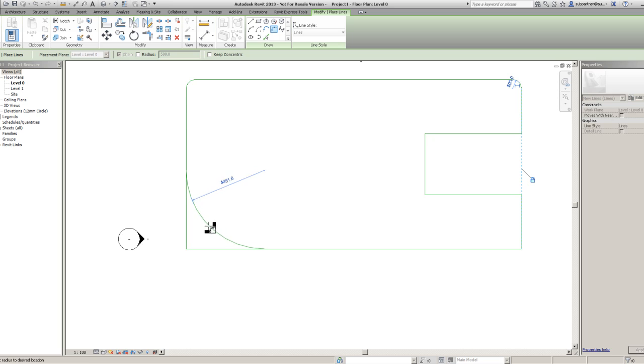Now the first thing you know, as it's moving, the dimension's changing. But very unlike most of the things that it does in Revit, it's actually quite rough. Now normally what happens is it obviously rounds it up or rounds it down to the closest 100, 20, depending on how far in you're zoomed to that. Now obviously, as you can see, it's doing it fairly rough. Now watch what happens when I actually left click. No fear, it does still round it up or down, okay?